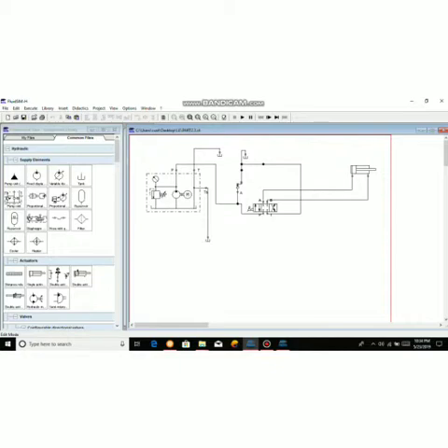Next, connect the check valve to the tank. For the 4/2 way connection, A and B will connect to the two double acting cylinders. So it will run like this.